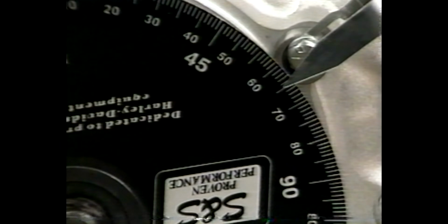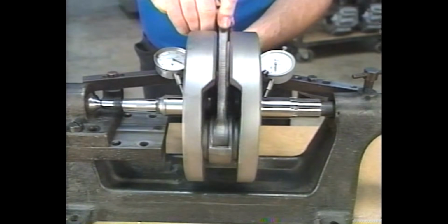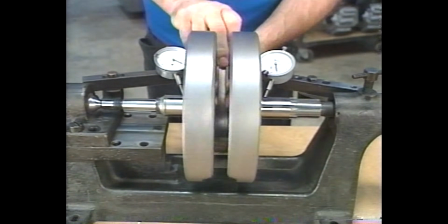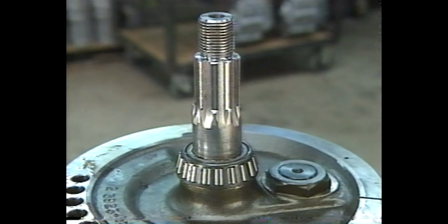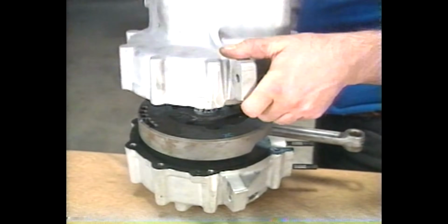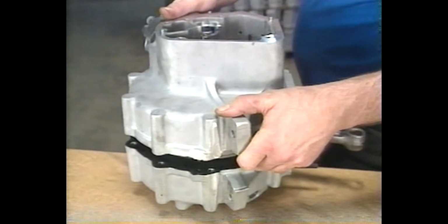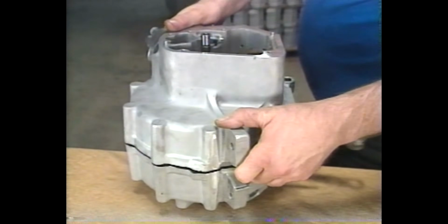Remember, if we have to adjust our camshaft by more than 4 degrees, we have the wrong cam and must select another one. The tolerances and clearances we used in assembling the crankshaft and the bottom end in general will vary enough to greatly impact our camshaft timing in relation to our engine. This is why we must degree our cam to our particular engine configuration.